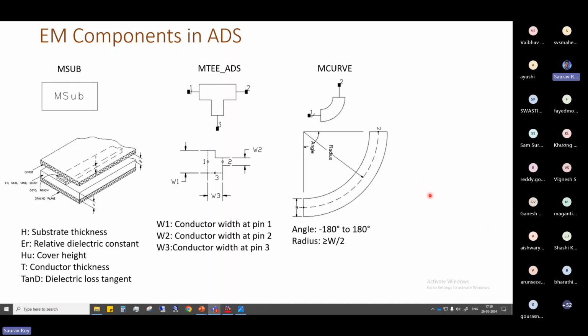Okay, so that's why they have a very generalized substrate which can be used for both strip line and microstrip line. In case of strip line, as you know, the conductor or the metallic patch will be inside, and both sides you will have a substrate as well as ground layer. But we don't go into that. In our case, we will have only microstrip line.